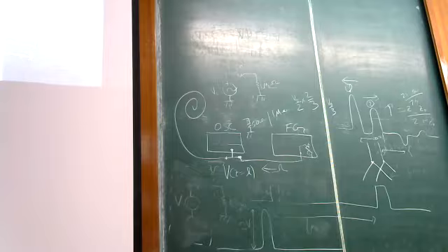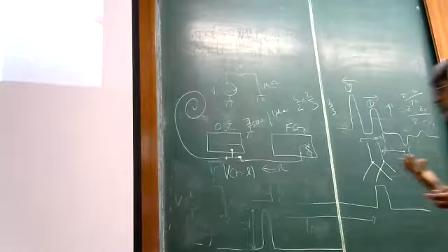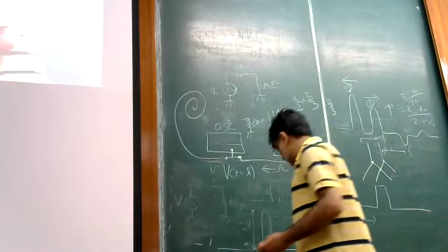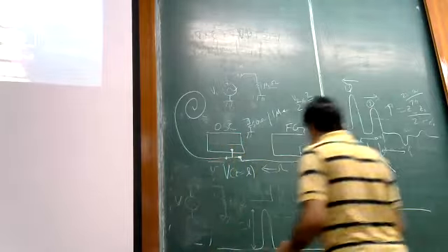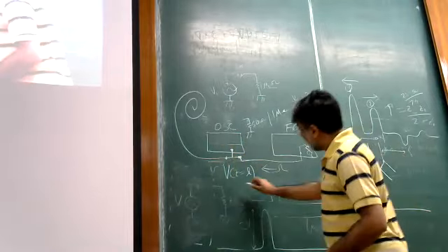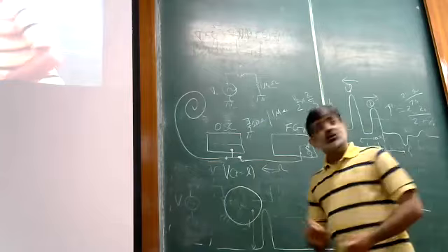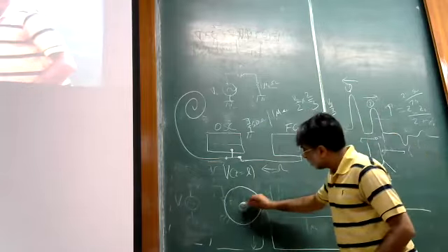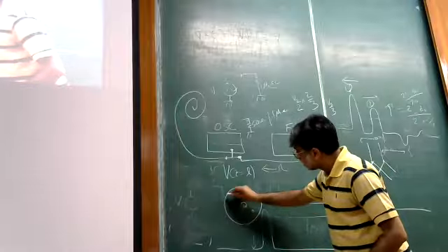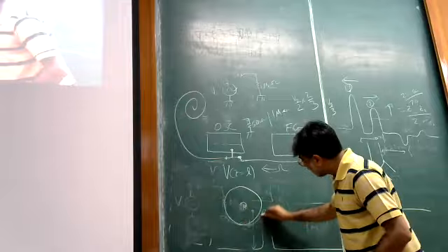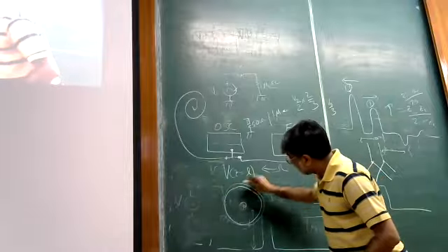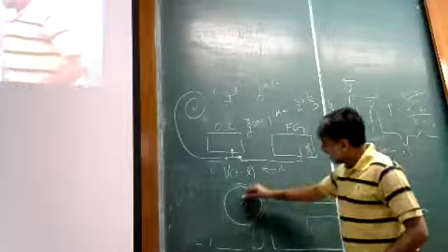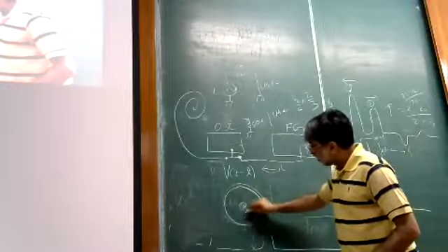So the most commonly used transmission lines when we connect instruments are going to be coaxial transmission lines. And a coaxial transmission line basically has an outer conductor and a center conductor. So these are both metals. So this will be like some thin shell like thing. And then here there will be some dielectric.